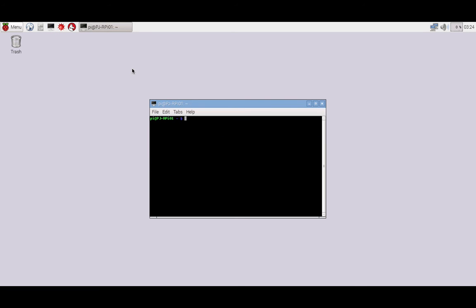Now that we have set up I2C and installed some tools to use it, we're going to make sure that we can detect what is on the I2C interface. To do this, I'm going to run the i2cdetect command, using -y to suppress any prompts to say yes I'm sure, and because I'm on a Raspberry Pi version 2, I'm going to specify bus number 1. If you're on an earlier version of the Pi, you'll need 0 here. I can see that I can communicate to the I2C bus, and nothing is currently detected.